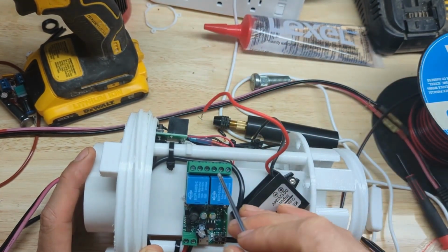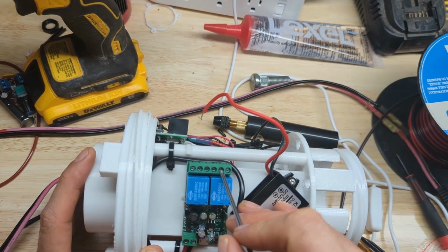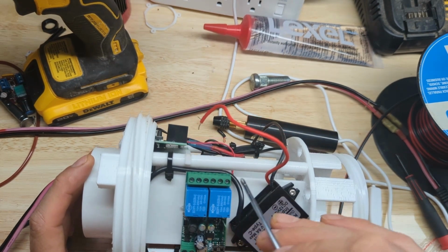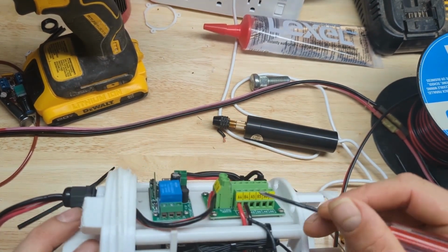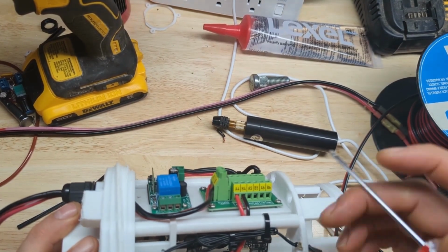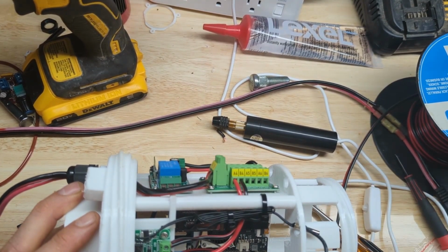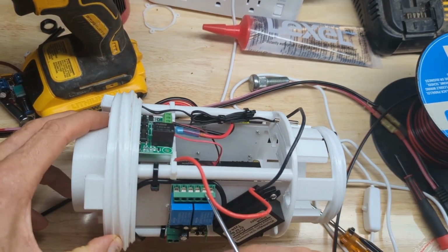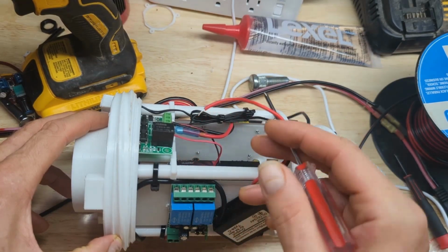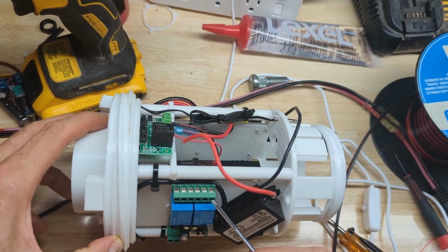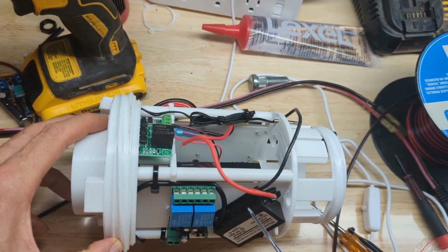Now the second screw, we don't use the third screw at all. The second screw, we wire that directly into our power block. So we will take a wire, run it all the way over, and connect it into either A5 or A6, depending on where we hook this negative up at. So basically, the second port, you need to provide a constant power source to this block. So whenever this relay switches on or off, it takes the power from that block and transfers it over to this little slot here. So it's got power coming out of it, provides power.